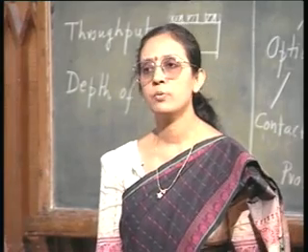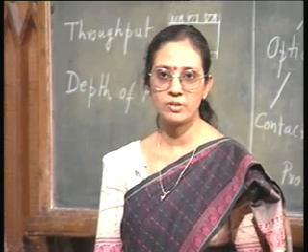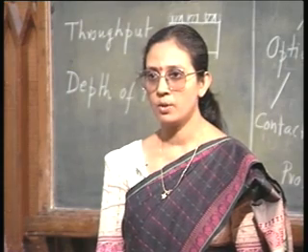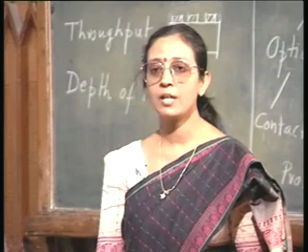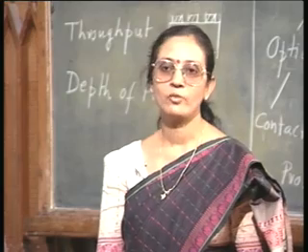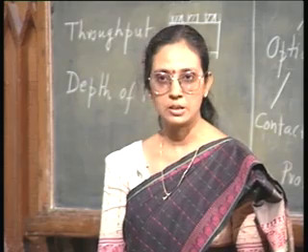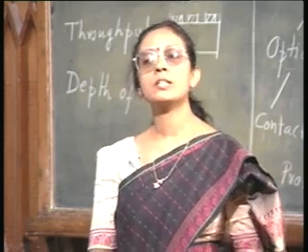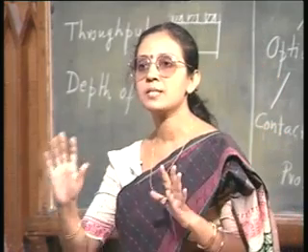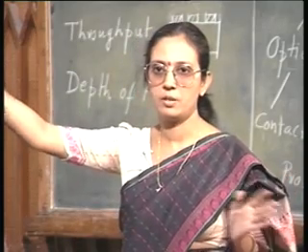But suppose you are not happy with this compromise, there are some perfectionists who say that I want the best of everything. I want to have my cake and eat it too. I want good resolution and I also want my mask plate to last a very long time. Well, for them also we have a solution, and that solution is the projection printing. In projection printing, the concept is very interesting. Here the mask is nowhere near the semiconductor. Mask can be here, wafer can be here. There can be a mile separation.